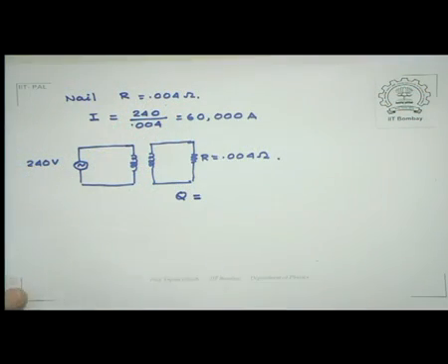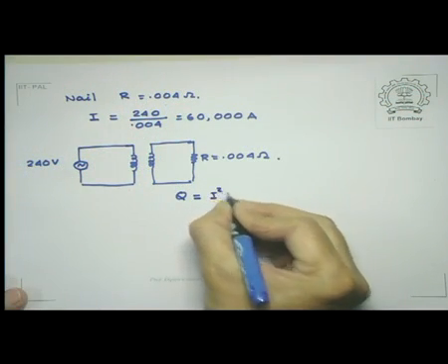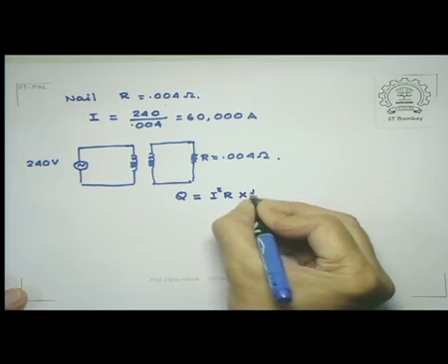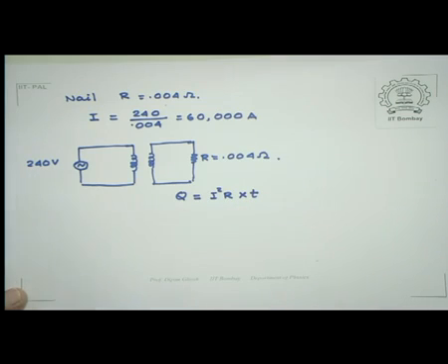Now suppose I did that calculation, then my Q, that is the amount of heat that is required, is given by I square R times the time, which, let me take it to be a couple of minutes for convenience, and I can easily calculate how much current I require, because everything else is known to me.